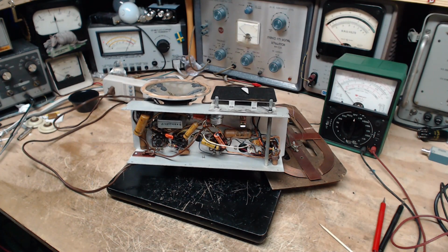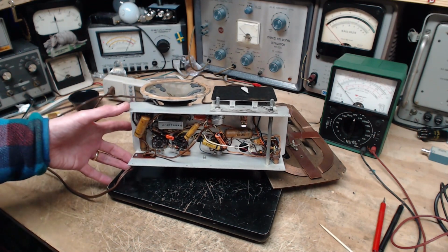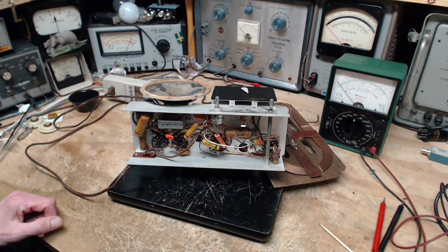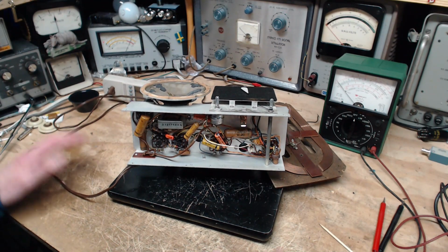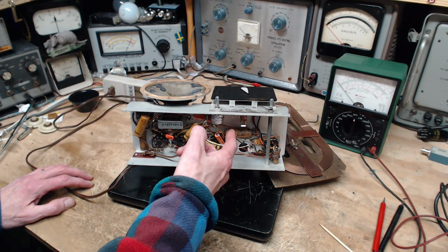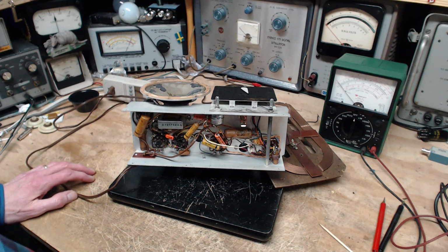So in the fact that you touch the chassis, you can get a shock, particularly if you're touching this and something else, whatever that might be. Maybe another radio, maybe, who knows. So there is a concern here about how much current is leaking through a capacitor like this, and is it enough to make the situation dangerous.